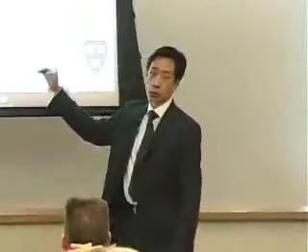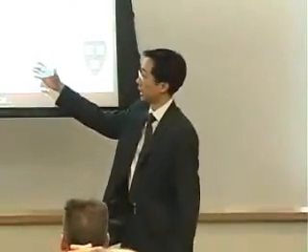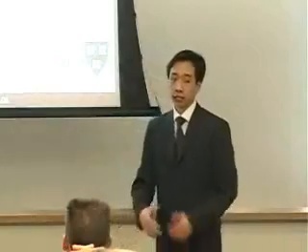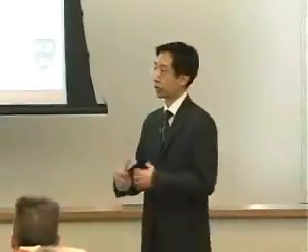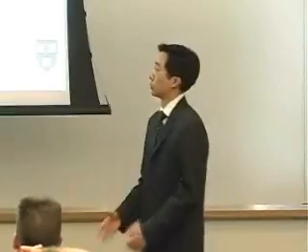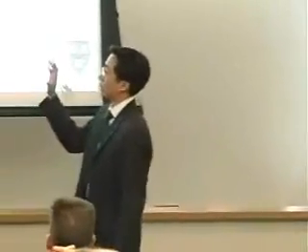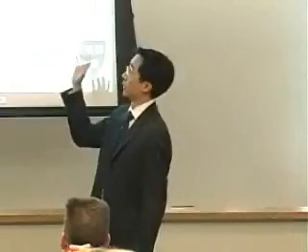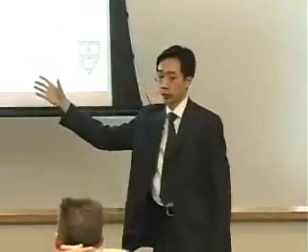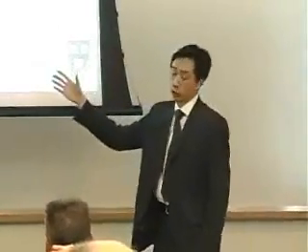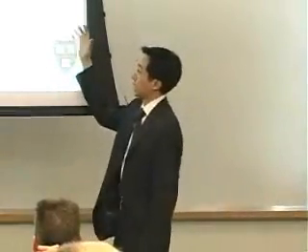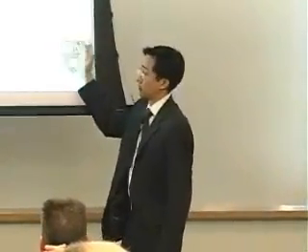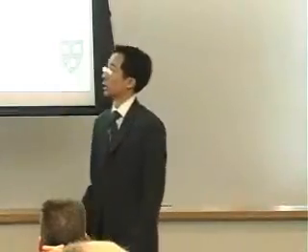If you've never seen box plots before, the bottom of the box is the 25th percentile, the red line is median error, and the top of the box is the 75th percentile. And there is some statistical definition of what constitutes an outlier that I won't go into, but you can certainly ask me about it. But at a high level, what we observe here on the figure on the left is performance errors. So we're looking at simulator-reported performance numbers against regression-predicted performance numbers. And the figure on the right shows the power errors, the error distributions.